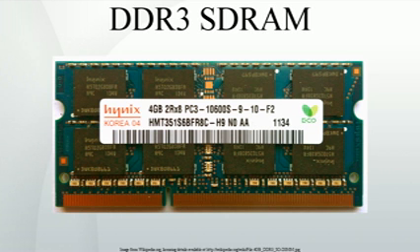All RAM data rates in between or above these listed specifications are not standardized by JEDEC; often they are simply manufacturer optimizations using higher tolerance or overvoltage chips. Of these non-standard specifications, the highest reported speed reached was equivalent to DDR3-2544, as of May 2010.